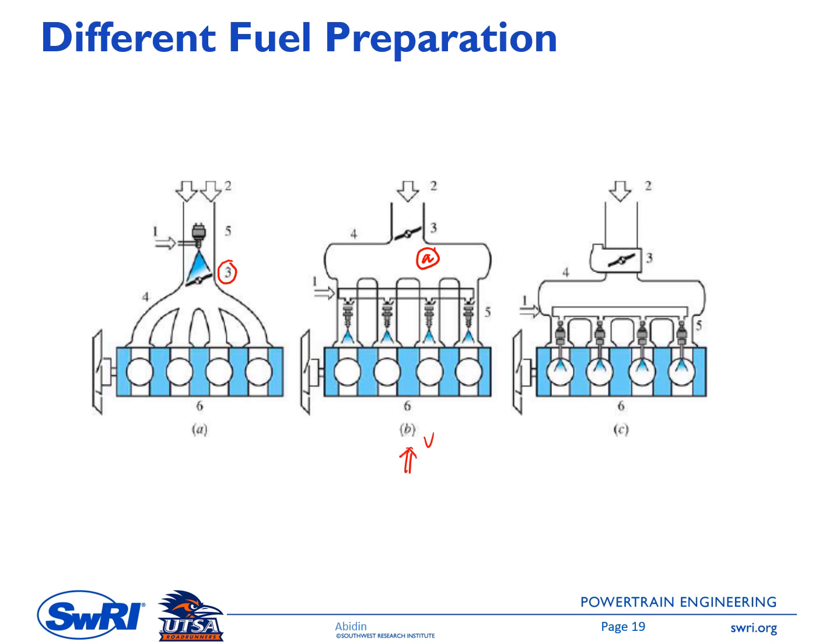And then some of the modern engines introduce the fuel directly inside the cylinder. Each cylinder has one injector, and once again the fuel is introduced directly inside the cylinder. The fuel injection occurs during the intake stroke, or during the early part of the compression stroke if you want to have fuel stratification during the combustion process.